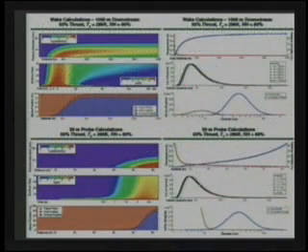The other thing that I don't have time to talk about is that to try and understand this, you can only measure so many things. We're also doing a fair amount of modeling and trying to understand what goes on as the exhaust evolves downstream so that we can help interpret the measurements that we're making at the engine exit plane and relate them to what happens downstream at 50 meters or even further downstream. And this is some results of our modeling work. One of the important things that came out of that is that the modeling work identified that we had to worry about particle processing that was going on in the probe as well as what happens in the exhaust. It turns out that when you measure at 30 or 50 meters, the amount of time spent in the plume is so short that the microphysical processing hasn't been completed, and some of it was continuing to happen as it went to our instruments.